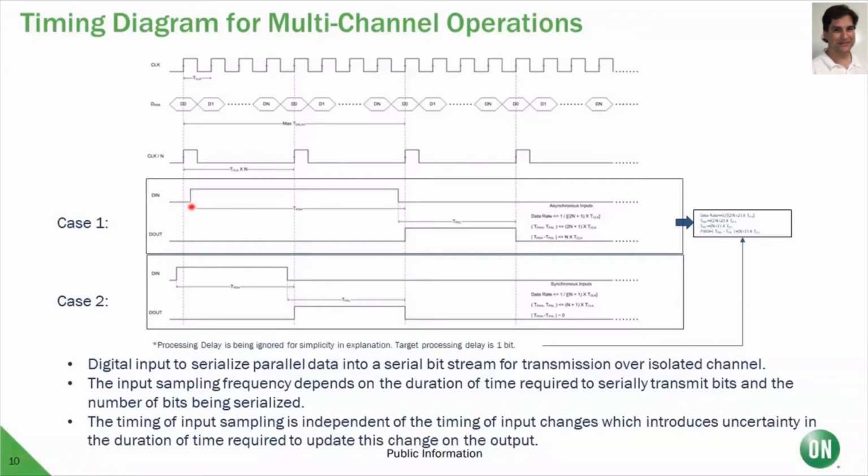There is an option to offer a clock pin so that you can use that to feed in your external clock signal and synchronize the data. That eliminates that chance for the data to arrive after the sampling occurs. And then you can reduce the pulse width distortion to about 1 or 2 nanoseconds.